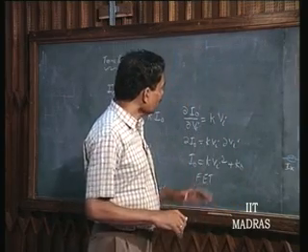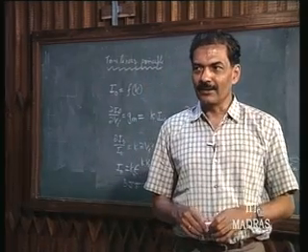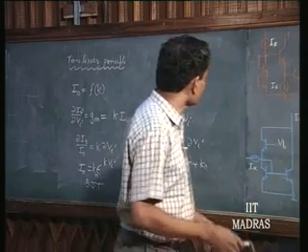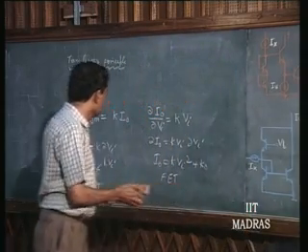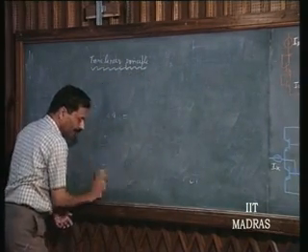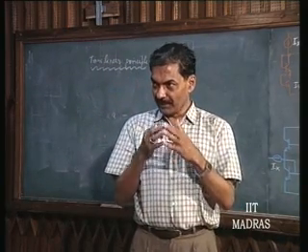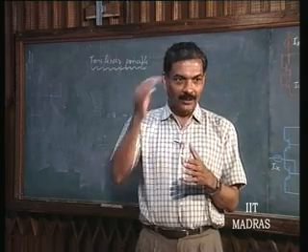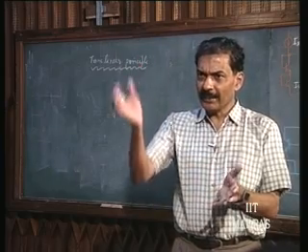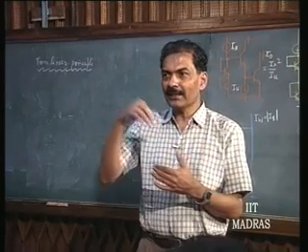And therefore, what is it that we can do mathematically with this principle of translinearity? Lot of things in signal processing. That is all about analog signal processing. Let us see. We just said that when we connect equal number of diodes or base to emitter junctions in clockwise direction as well as anti-clockwise direction in order to form a loop, they can be connected in any random fashion, but there should be equal number of diodes both in clockwise direction as well as anti-clockwise direction.